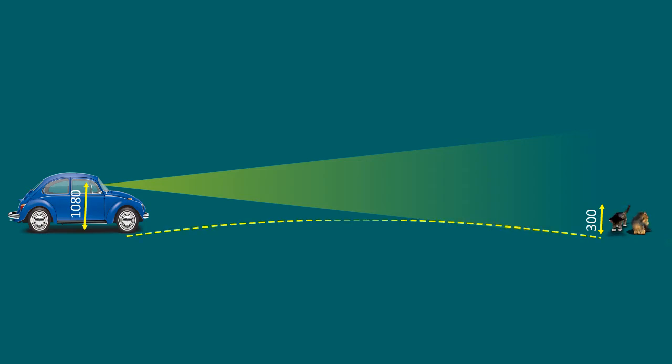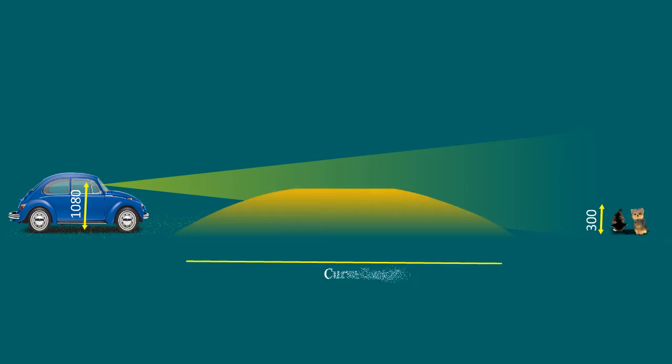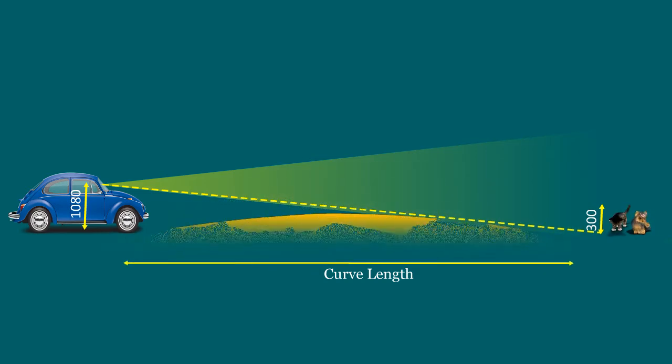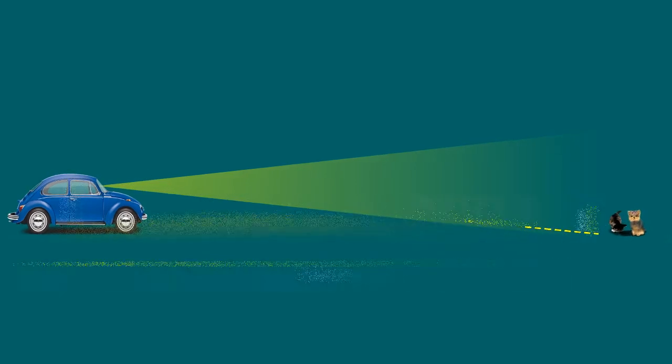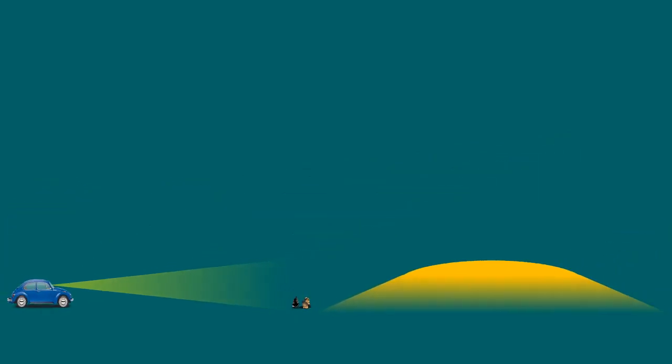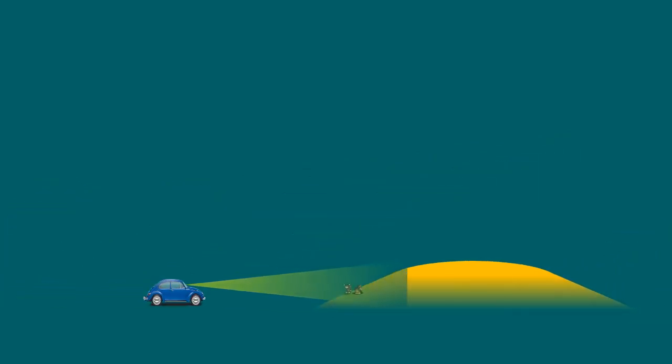That means, while designing, we must take care that the difference in profile levels shall not be more than this limit within this sight distance. In case this difference is more than this limit, and objects are not visible within this sight distance, then we have to increase the length of the vertical curve by reducing the value of the rate of change of grade, R. Hope you understand the importance of stopping sight distance.